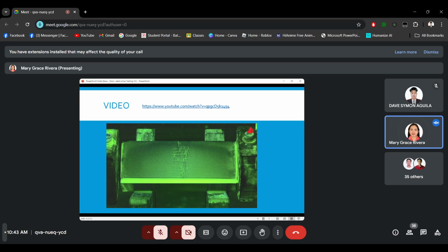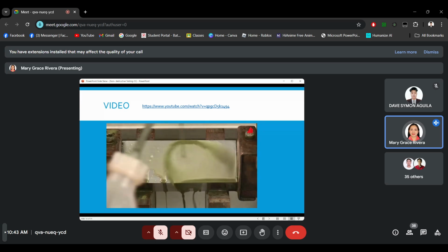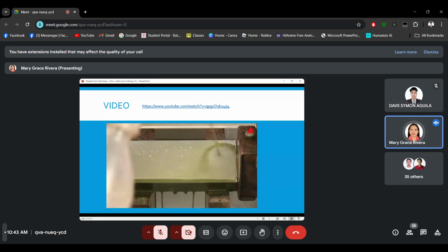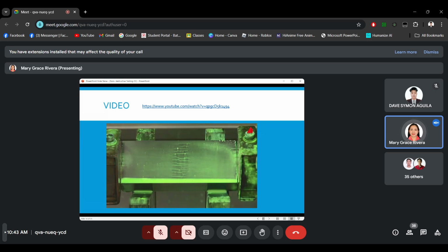To do this, the material tester switches the machine over to the current flow method. A high electric current flows through the sample, generating a circular magnetic field. Now the cracks in horizontal direction can be seen very well. The tested sample is a hardened sliding guide. The cracks have been formed during the hardening process and the subsequent grinding operation.